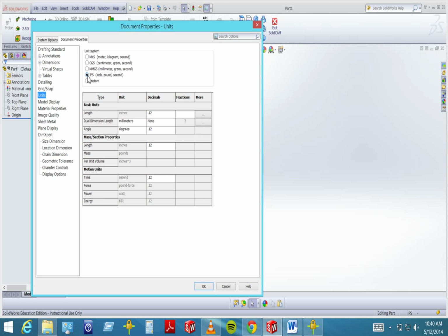The second thing is fasteners and other types of conventions like pipe sizes, tube sizes, thicknesses of sheet metals and plates and all that kind of stuff. In America, they still have imperial units. It would cost way too much to retool all these factories to build all those things in metric units. So you get a lot of 1/4 inch bolts and 18 gauge thickness sheets and on and on and on, and 1/8 inch NPT pipe, which isn't 1/8 of an inch in diameter.